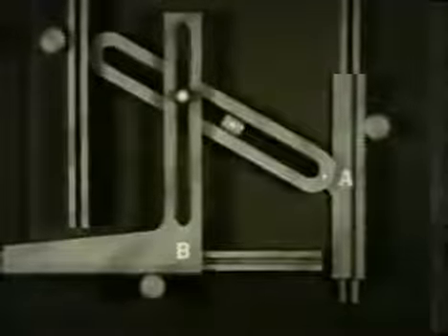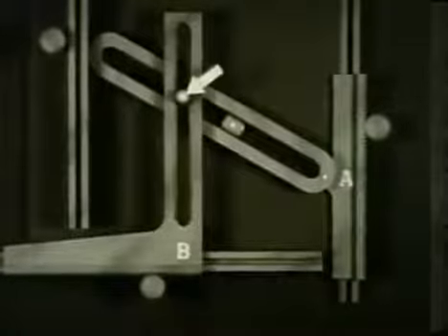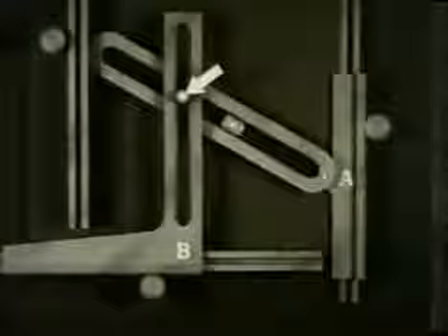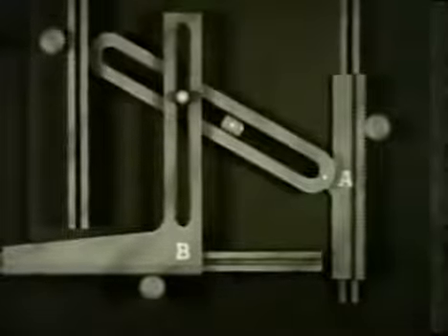The other input rack has a slot which is engaged to the pivot arm by a sliding pin, called the multiplier pin. When either input rack moves, it changes the position of the multiplier pin. This pin also engages the slot of the output rack.